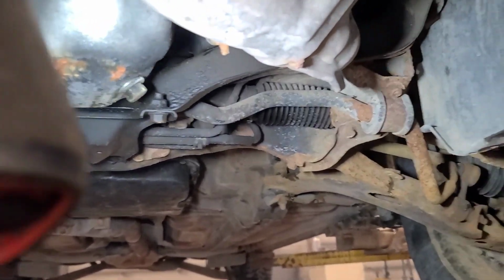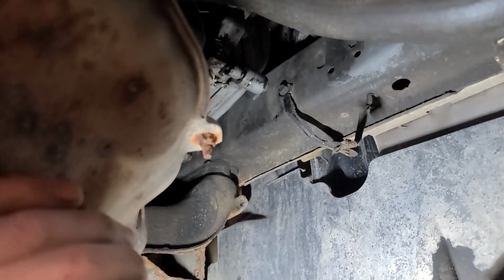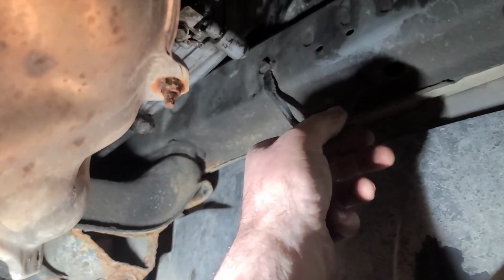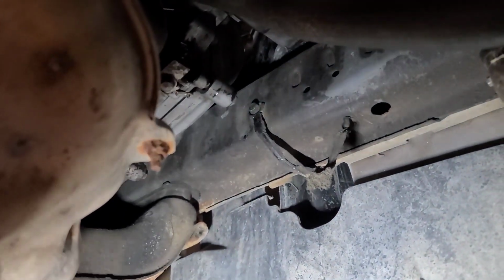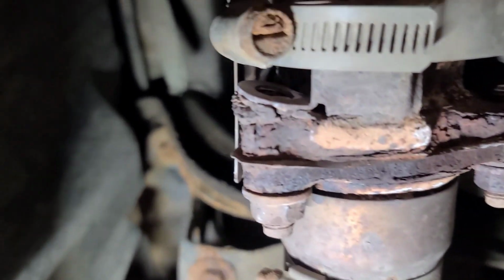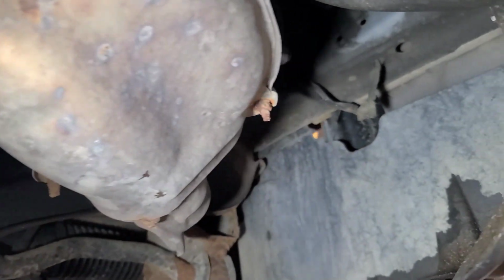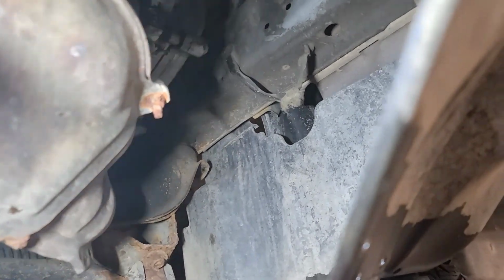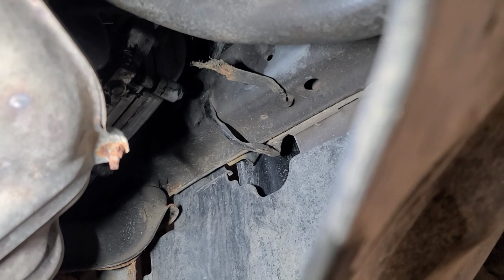So I know these Subarus have ground straps on the engine, one on each frame rail. And you can see this one is rotted off. Now the shop that just put this engine in should have fixed that. They're there for a reason. Body grounds. There's one on this side, and it's rotted off as well. Now, why wouldn't you fix that when you did an engine R&R? I've commonly seen them like this, and it didn't appear to have any problem, but this ignition coil seems to be very sensitive to low voltage, and any voltage drops in the circuit could be causing it.